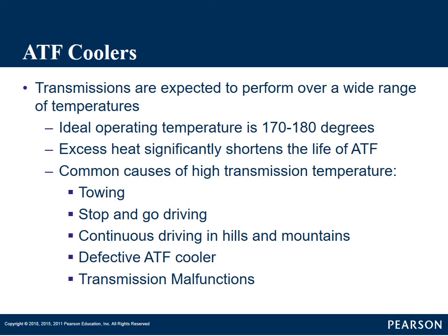Kind of your ideal temperature of an automatic transmission is about 170, 180 degrees. That is where they want to get that transmission temperature to. It's not too cold, not too hot. Excess heat destroys a transmission. This is probably the number one killer of automatic transmissions, is excessive heat.